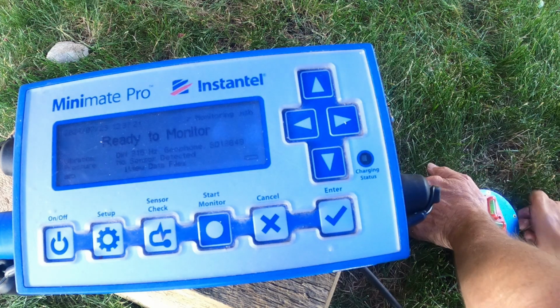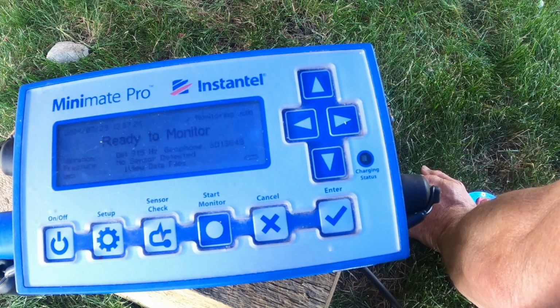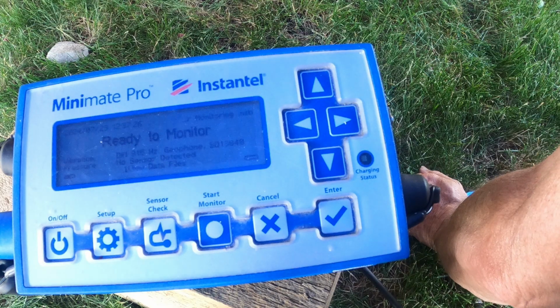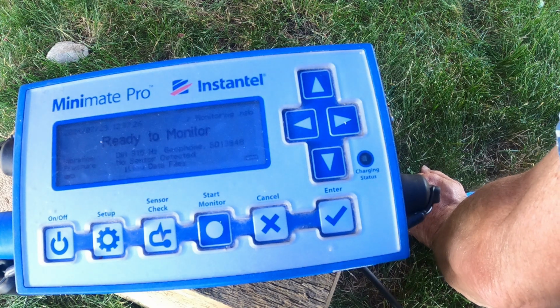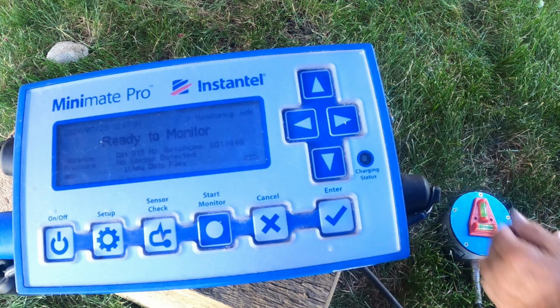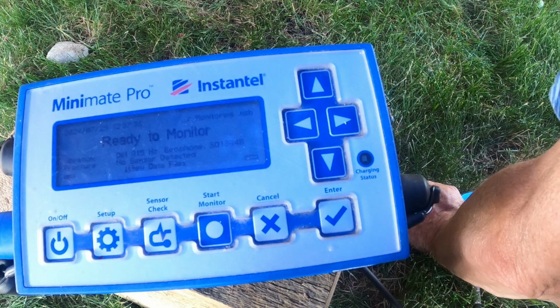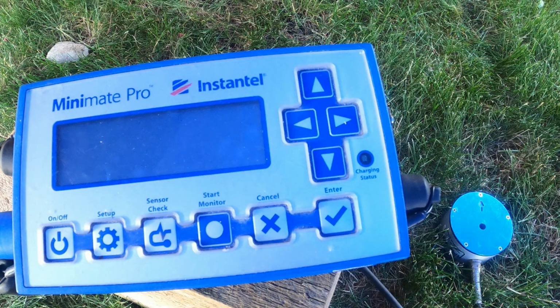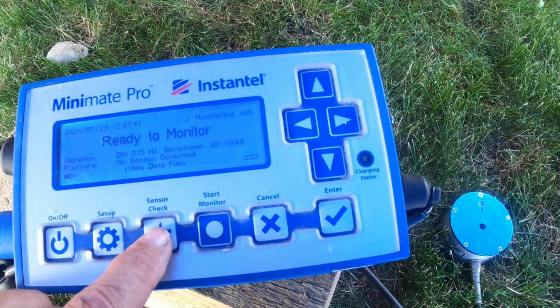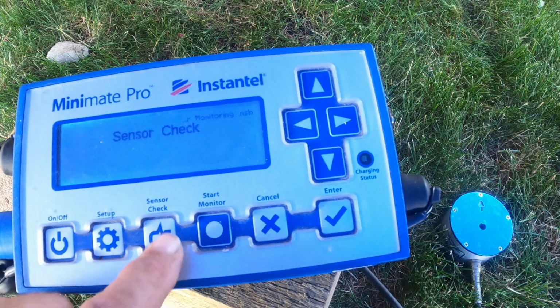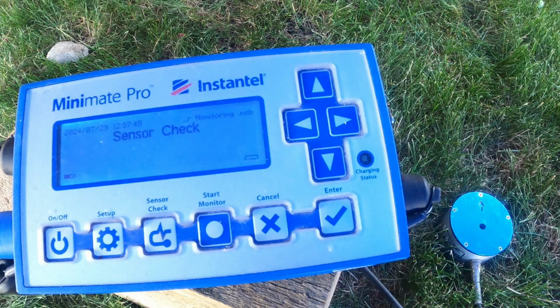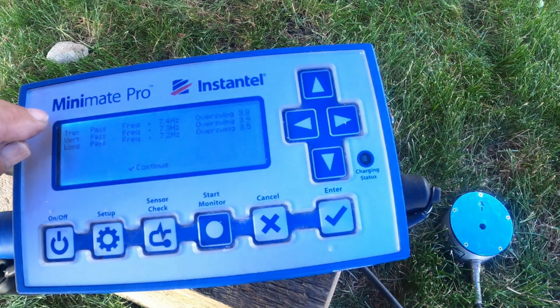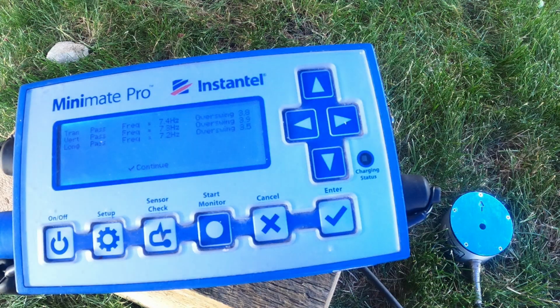So I always use a 2-axis level and use that to get it properly mounted and secure. You can use a single bubble level and just move it back and forth until you're correct, but that's typically what I would do. So then I would do a sensor check on this, and it'll pulse all 3 sensors and compare the results with what it expects, and in this case I can see it's passed on all 3 axes.